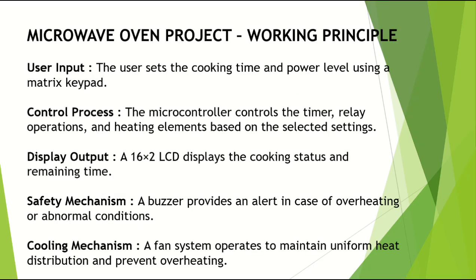The microwave project has these working principles. User input: the user sets the cooking time and power level using a matrix keypad. Control process: the microcontroller controls the timer, relay operation, and heating elements based on the selected setting. The display is a 16 by 2 LCD display. Safety mechanism: a buzzer provides an alert in case of overheating or abnormal conditions, and we also use a cooling fan when we need it.